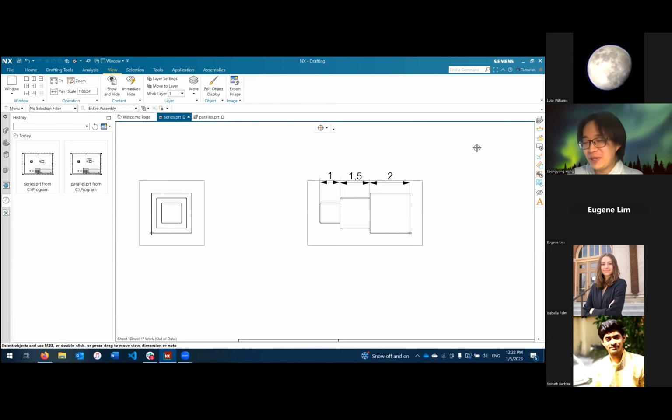So my question was, when you're talking about linear tolerances, you mentioned there are two types. There's plus or minus tolerancing, where there's a nominal and then you want a range around that. And there is one where you just have a min and max, and there is no nominal. That's correct. Yeah. So I guess my question is, when you're actually machining it, does that make a difference? Why do we forego a nominal? Are there cases where that's beneficial?